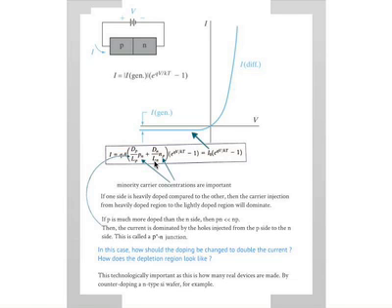So you have an I now that is essentially proportional to some term times Np plus some term times Pn, times all the exponentials. Let's ignore that for the time being. If Np is far smaller than Pn, that means p-type is very heavily doped, so there are very few electrons. That means this term cancels out, basically. This is too small. So the only control you have in terms of doping is now on the lightly doped side, which is a little bit counterintuitive.